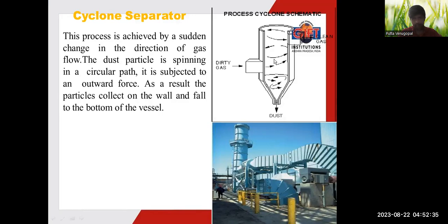When the air enters, the weighted particles swirl. The heavier particles come down, and the clean gas or less dense air stays at the top. Whatever has high weight falls down, and the remaining light part settles at the top and exits as clean gas from this particular point. In these devices, we use a mechanical system like a blowing system to absorb the particulate matter, stopping it from entering the atmosphere.